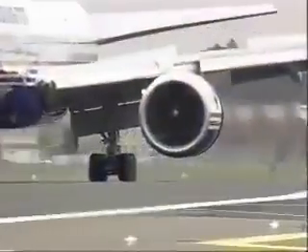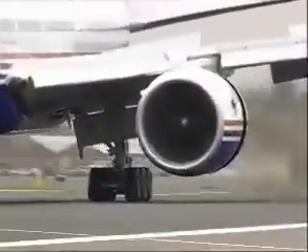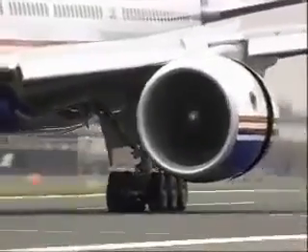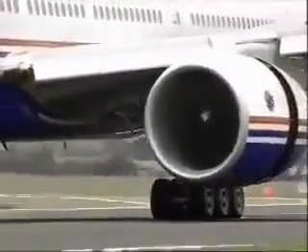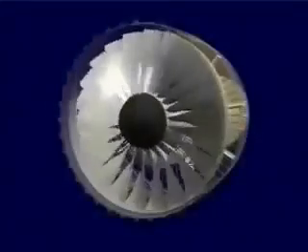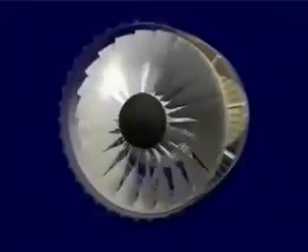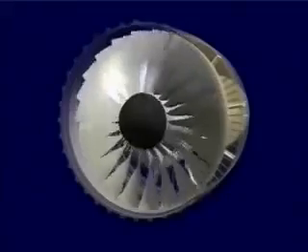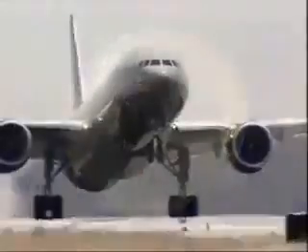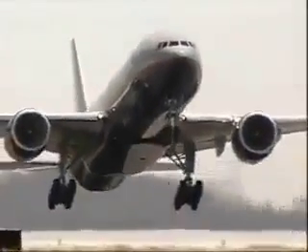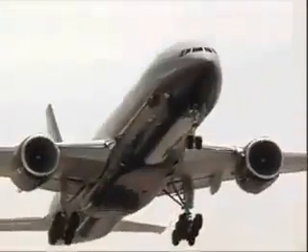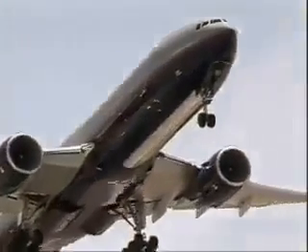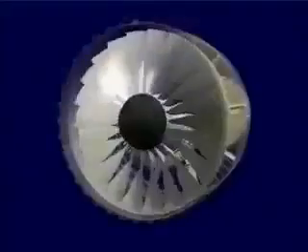To see how this thrust is developed, let's look at the internal workings of Pratt & Whitney's PW4000-102 turbofan engine. The first component in the engine is the huge 9-foot diameter fan that rotates 2,800 times a minute at takeoff. This giant fan sucks in enough air to vacuum out the air in a 4-bedroom house in less than half a second. As the air races through the massive fan, it's separated into two streams.